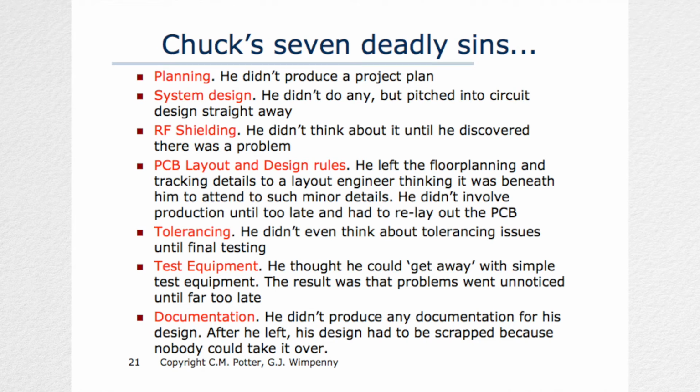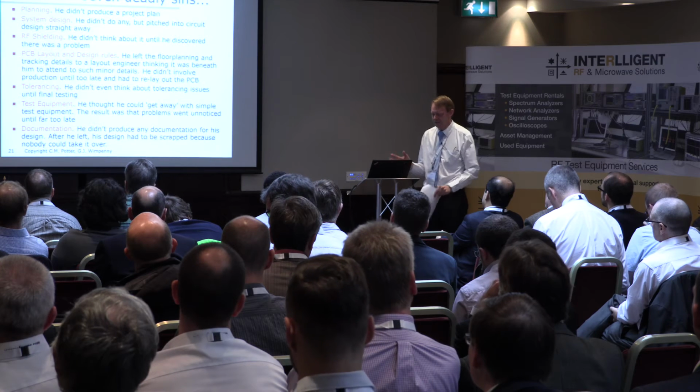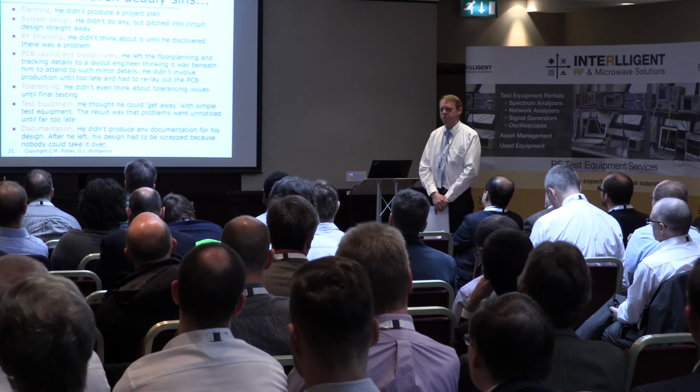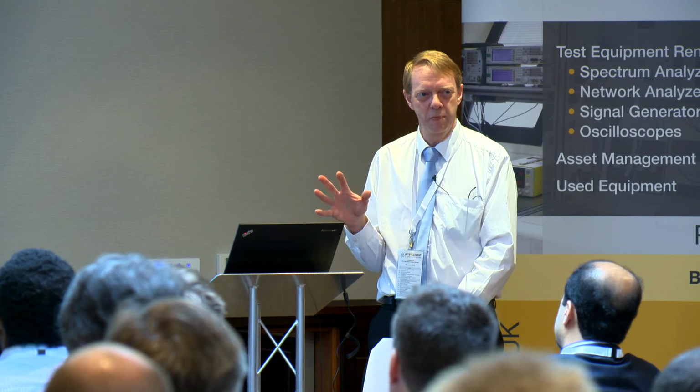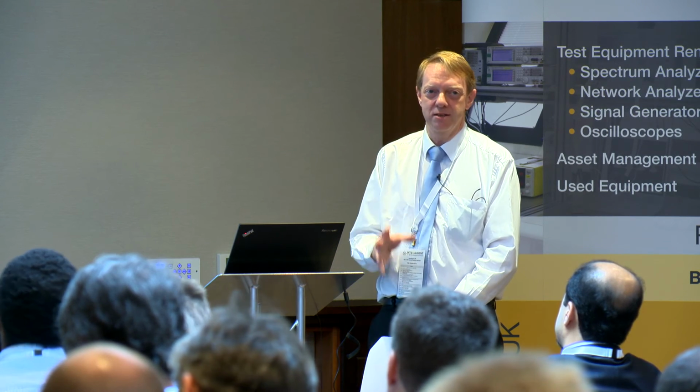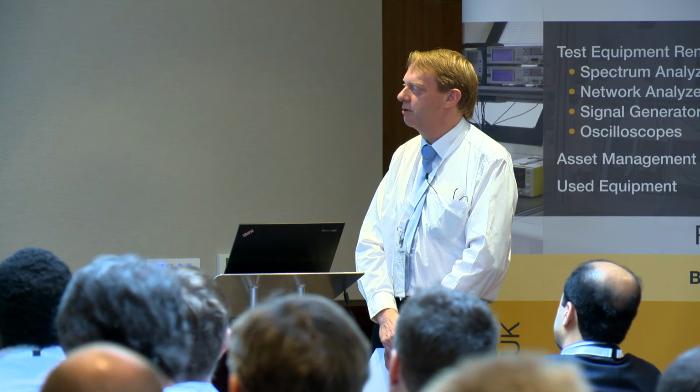So the layout details and the design rules, I mean, by leaving the floor planning and tracking details to a layout guy who is good at laying out but not necessarily good at RF, may be an issue. And this particular thing is one of my particular pet hates. I always find I have to sit next to the guy doing PCB layout, and between the pair of us we can satisfy both manufacturing rules, PCB layout design rules, and the possibility of getting the RF to work correctly as well.